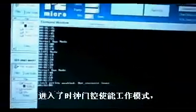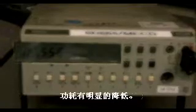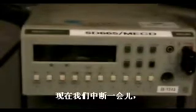You can see in my terminal that we've gone into the clock gating, we've enabled it, and our run currents are lower. If you take a look, we went from 4.5 to about 3.5 milliamps. So quite a significant difference there, depending on what your system is doing.